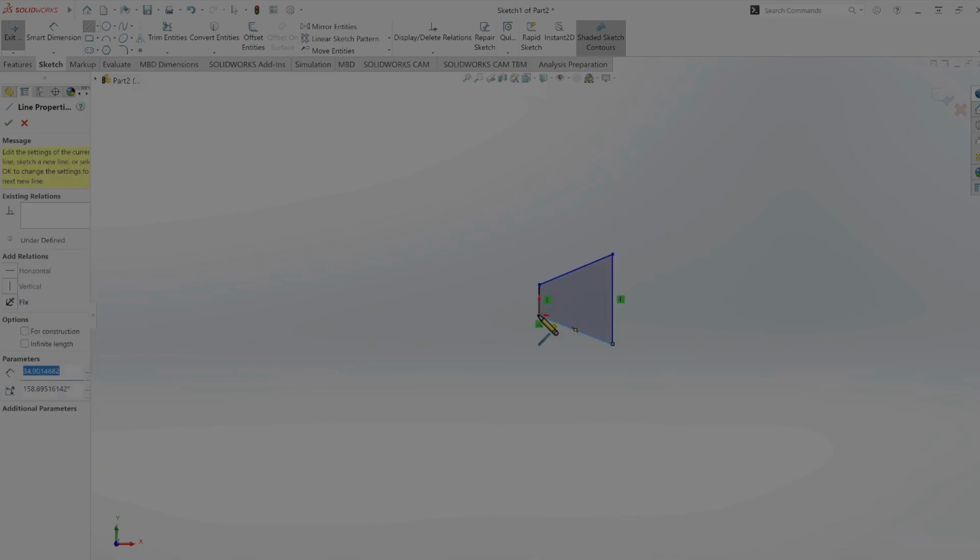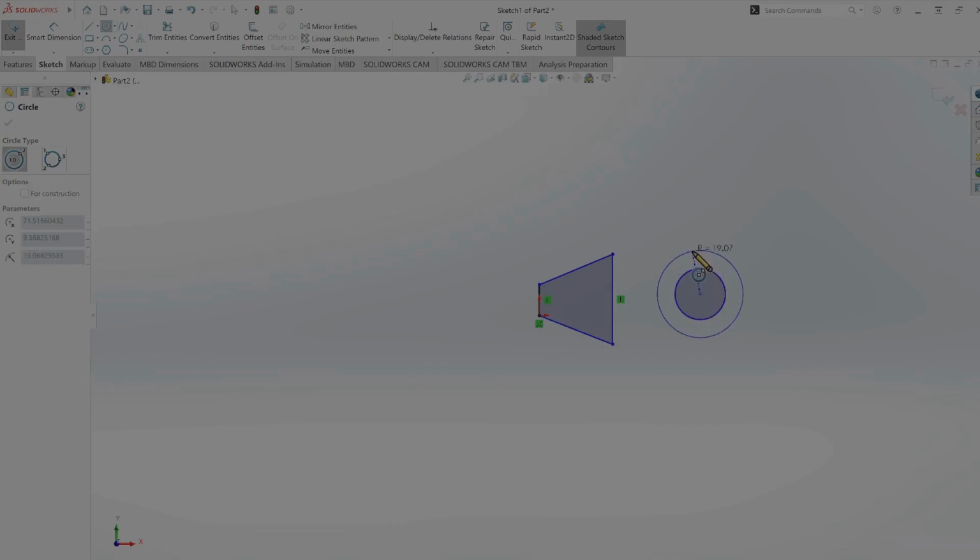You can think of it this way. In first angle projection, the object is between the viewer and the plane. Okay, so it means that the plane is behind the object. And then in third angle, the plane is between the viewer and the object. So now the plane is separating the viewer and the object.